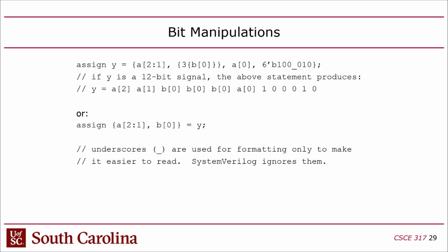I think the answer depends on the PWM frequency, and that's the reason why you can control that in your code. If the frequency is high enough, I think the LEDs have a capacitance that will act as a low-pass filter, but only up to a certain speed.